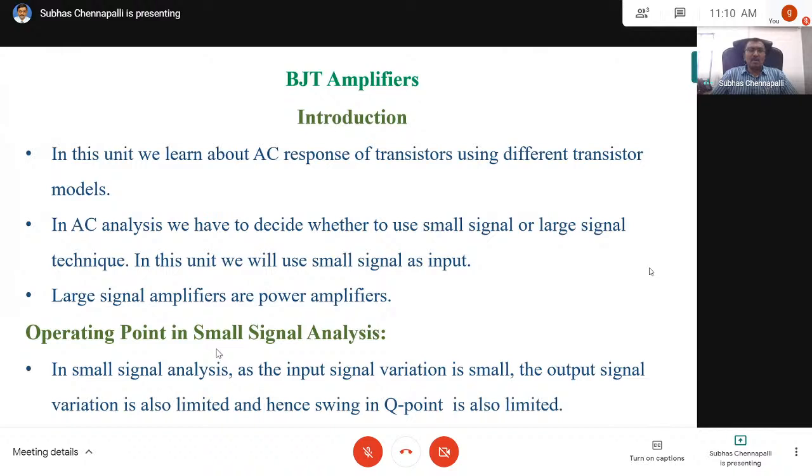So in one of the last classes, you learned how to draw the load line. You have refreshed your mind. DC load line, after that, AC load line. The AC load line will be steeper than the DC load line. When you apply AC input, for zero input current, obviously your DC load line and AC load line intersect at the Q point. The meaning is that when input is zero, obviously the AC load line has to go through the DC Q point. So that Q point is the same for the DC load line and the AC load line, but the AC load line will be steeper.